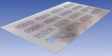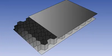The major structural components of the wing are generally manufactured from aluminium alloys, with composite material, such as glass-reinforced plastic or carbon-reinforced plastic and honeycomb structures, being used for more lightly loaded structures. Carbon-reinforced plastics are gaining wider acceptance for the manufacture of major structural components, such as the fin and horizontal stabilizer.